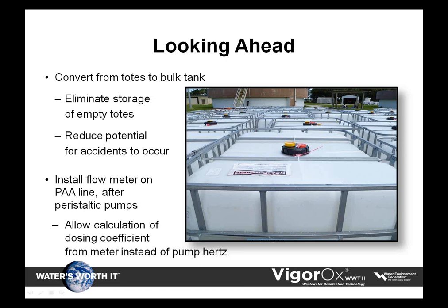We're also working to have a flow meter installed on the peracetic acid line just after the peracetic pumps. This will allow us to calculate our dosing coefficient from an actual meter instead of using the pump hertz, which is what we're doing now. And that's it.